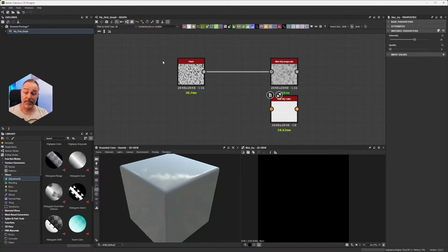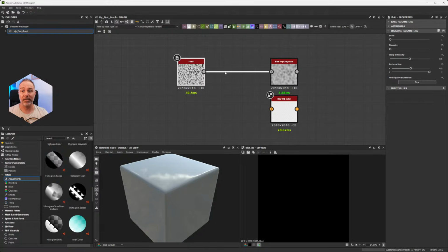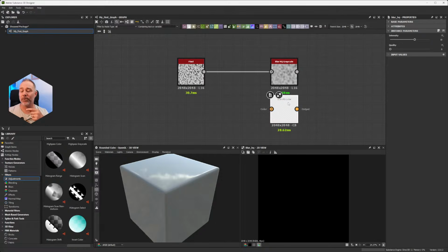Why? Because this one is a color node, which means that a grayscale node has one channel, a value from black to white, but on one channel. To represent color, we need 3 channels, and there is a fourth one as a bonus for the alpha, so it will contain the potential transparency of the image.